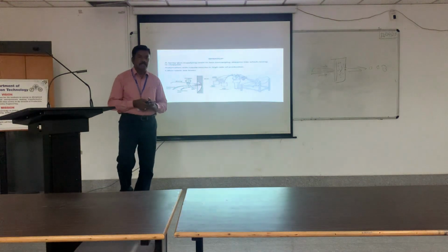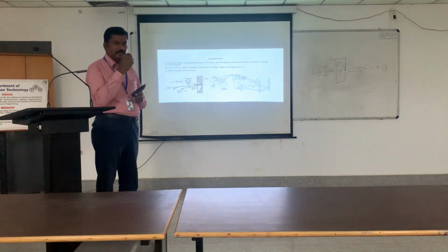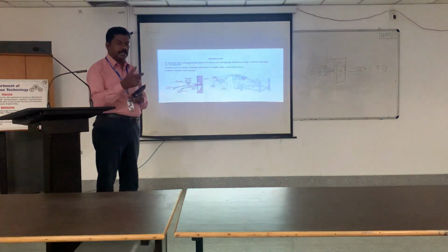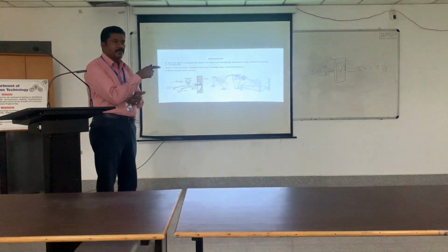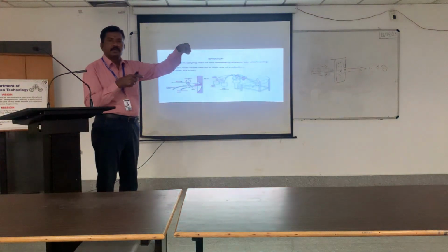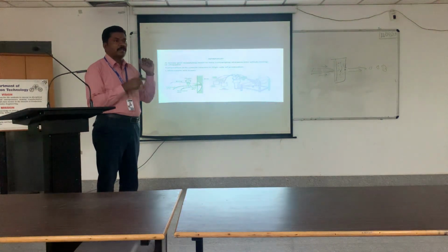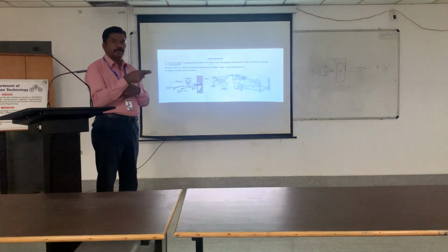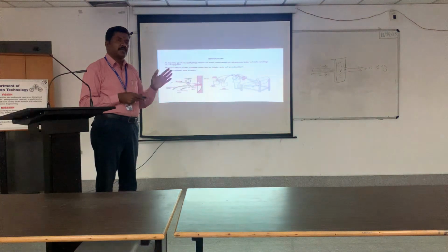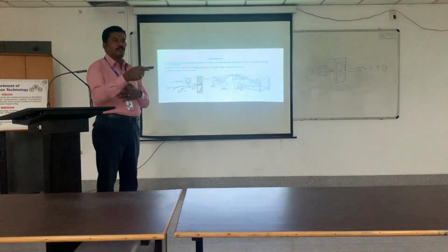Again the drawback is that it depends on the skill of the operator. If you instruct the employee to make a 10 mm thick plate, and each time he makes 2.5 mm, he has to move 4 times. So instead of moving slowly, if he moves fast, then on the top plate you will have a lesser thickness. Or if he moves very slowly, then the thickness will be higher. So the uniform thickness purely depends on the movement of the gun, which is done by the operator. So to slightly automate this process, they will use some kind of automated robotic mechanisms.